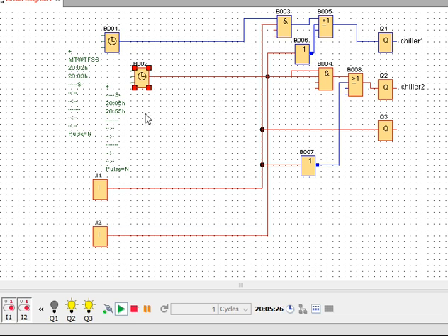So once the external relay is energized in the chiller, it will disconnect the command from PLC input I2, and here it will be de-energized, and here this will be de-energized as this is Q3. You can take the status from here and you can put any other status for I2. So I will make it off. Suppose you received fault on I1 and this will go off.